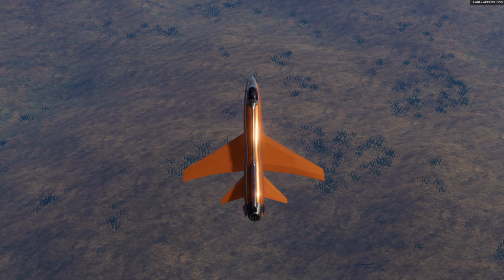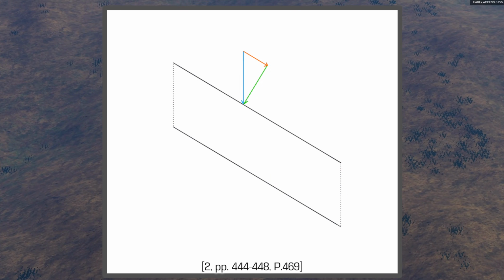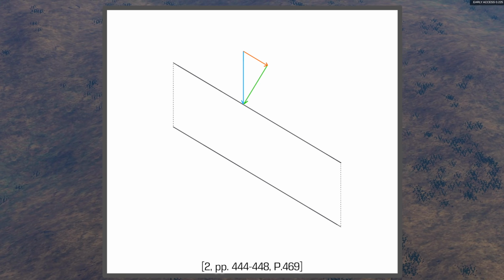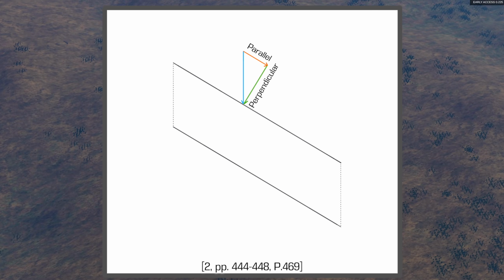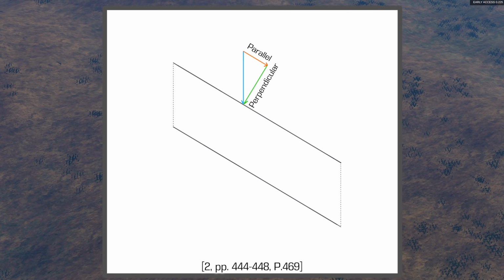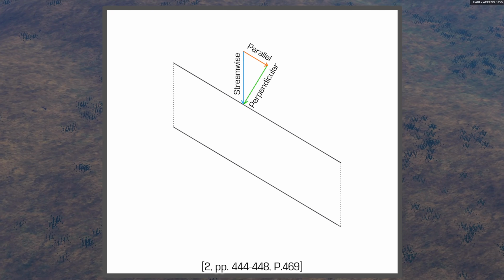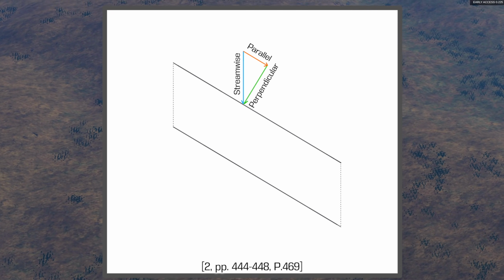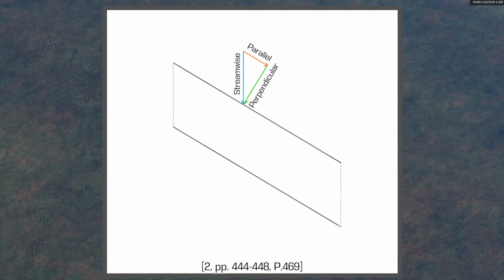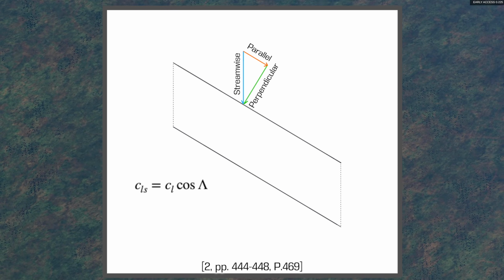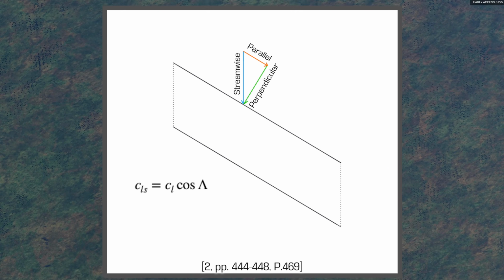A simplified look at sweep effects on lift is provided by simple sweep theory. When a wing is swept, the flow over an airfoil section of the wing is split into components parallel and perpendicular to the leading edge. The perpendicular flow component will have a lower velocity compared to the streamwise flow velocity, which lowers the amount of lift generated per a given angle of attack compared to an unswept wing. The sectional lift coefficient will be lowered by the cosine of the leading edge sweep for small angles of attack.